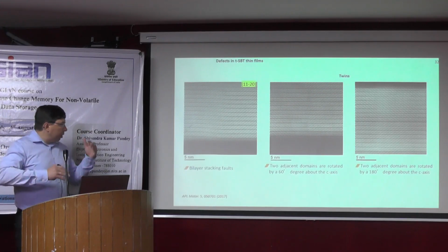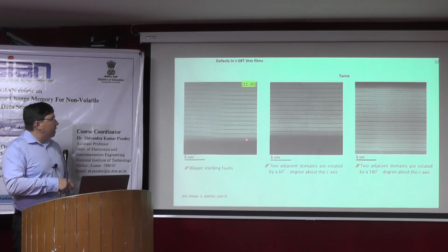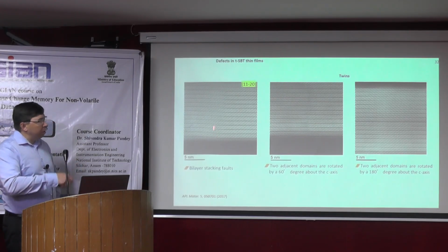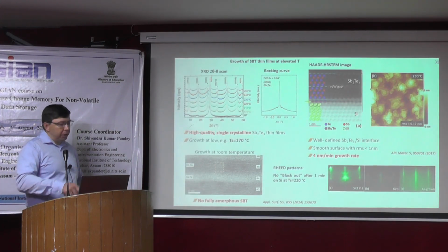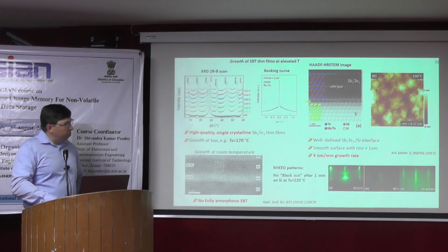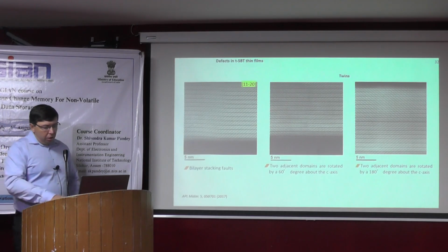like atomic steps here. And here we can see that some units start to form with a low number of layers. This is 2 tellurium layers, this is 3, and here intrinsically we introduce this bilayer defect. But this is already a defect. And if we combine it with the spiral growth of these materials, we can conclude that these bilayer defects, in this case, are dislocations.